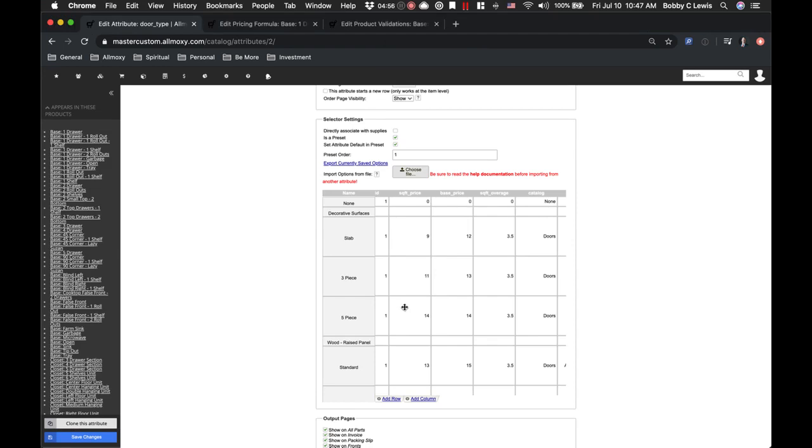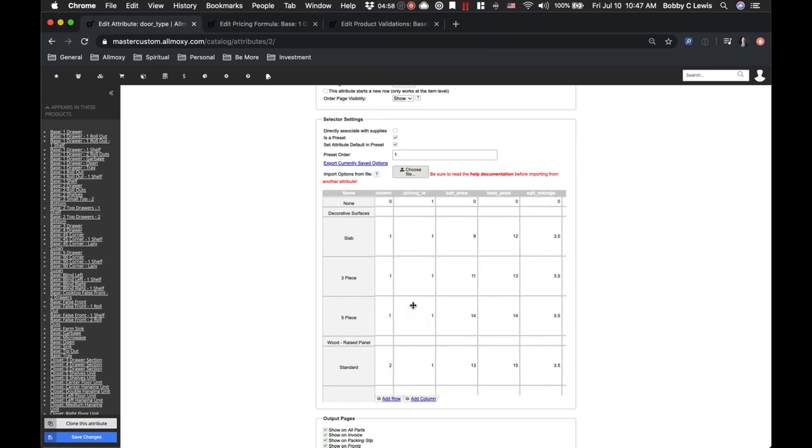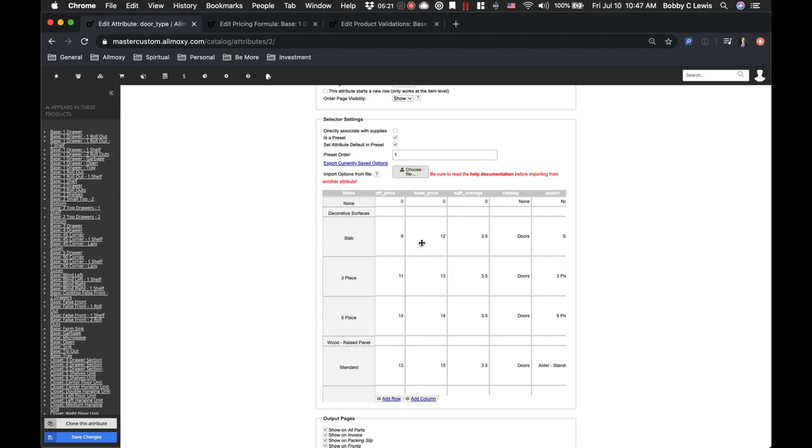Now, one thing to consider is if you are using a cost plus margin method, a number 2, pricing ID of 2, then you're going to have to change the margin over on the front material and finish, because that is where the material is determining your cost. So it's important that you use those fields there to determine your margin and the cost of your sheet material.